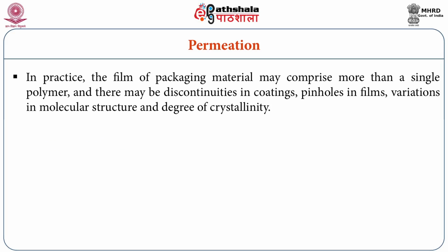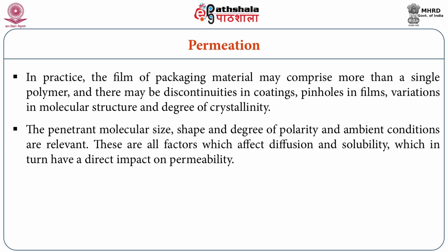In practice, the film of packaging material may comprise more than a single polymer, and there may be discontinuities in coatings, pinholes in films, variation in molecular structure and degree of crystallinity. The penetrant molecular size, shape and degree of polarity and ambient conditions are relevant. These are all factors which affect diffusion and solubility, which in turn have a direct impact on the permeability.